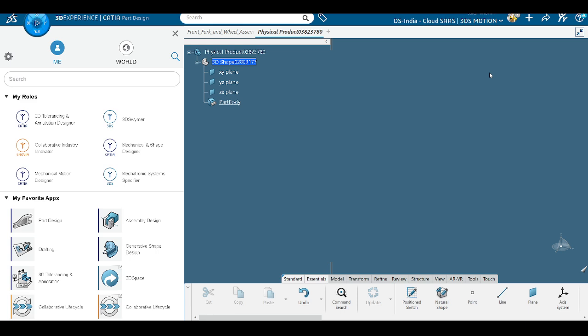Here in 3D itself, we can assign the annotation, we can give the datums, we can give the dimension, we can give all the datum features related, and it is standard compliant schematic information like your ISO standard, ASME standard, JIS standard. You can follow them by using the platform.